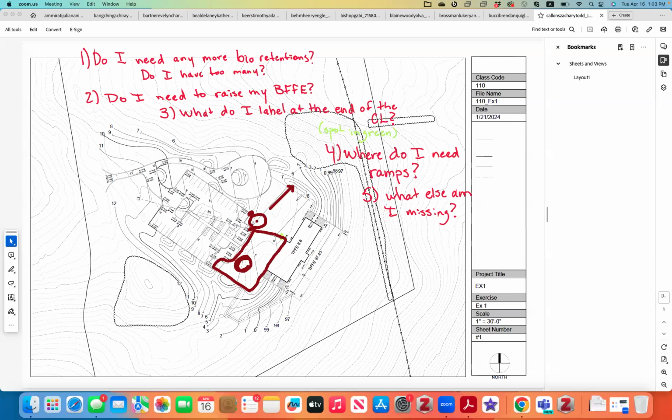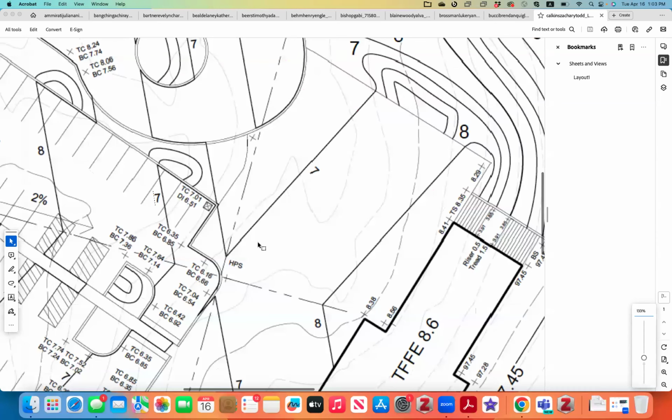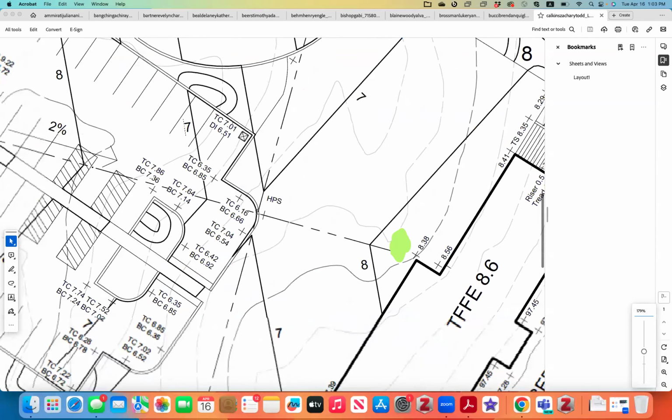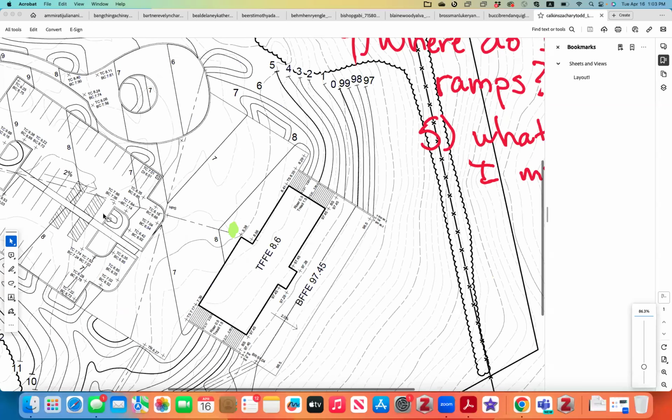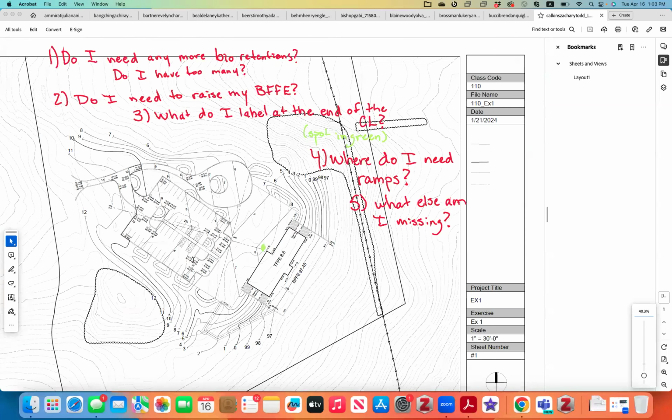Make it the shape of this, so it kind of collects more. All right, so one thing you definitely need to do is this thing in the middle. You see the water, it's kind of pounding over here, so you need to cut this open and have something over here. That's the first thing, and the other two things are cutting more holes in your plaza. That's the retention you need. Overall, good location of the retention areas.